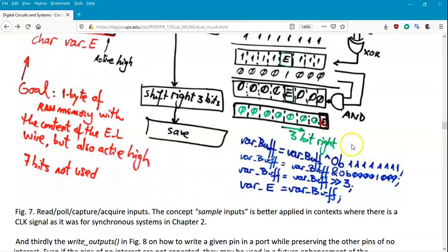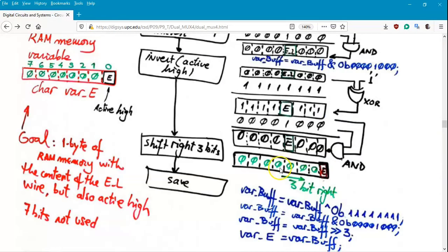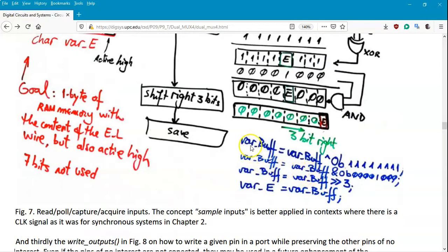And now, what goes here is the translation of this bitwise into C. So the first one was the not, but with this mask, which is this literal, 0xFF, you see, it is a not, bit by bit. And then, well, you can do that in many ways, naturally, but I'm explaining you one way, so that's a good thing. You know how to do it, even perhaps if it's not the best way. It doesn't matter. In the end, you know a method to do it. Then, you know, you have an AND with the mask, and then if you like to go shifting bits to the right is that instruction.